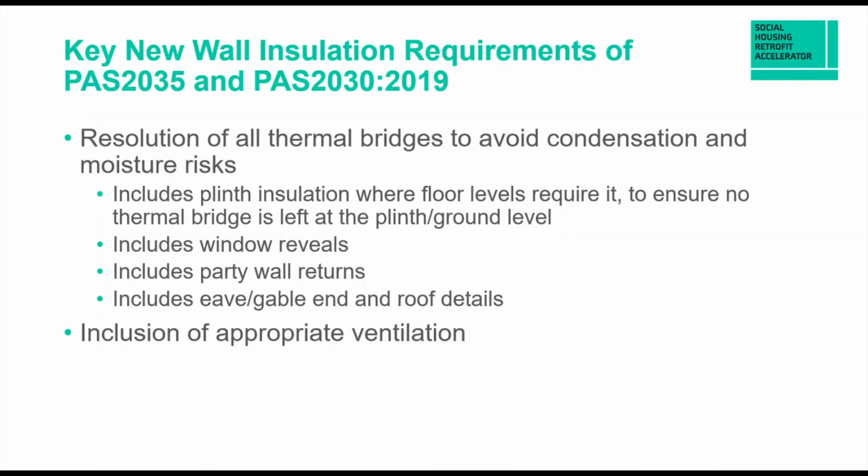So one of the key things that needs to be dealt with is PAS 2030-2019 for EWI requires the resolution of all thermal bridges to avoid condensation and moisture risk. We have to be able to demonstrate that we have adequately resolved the thermal bridges.